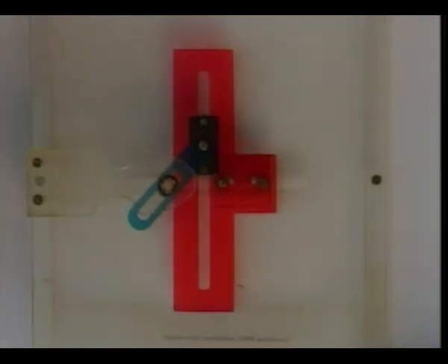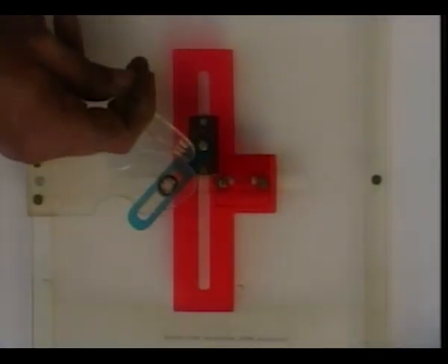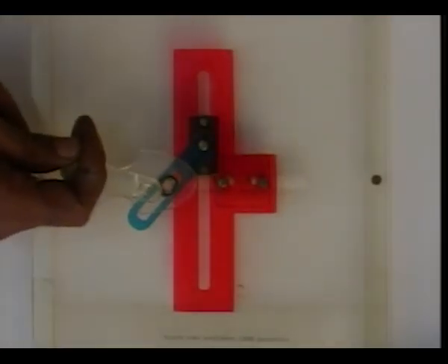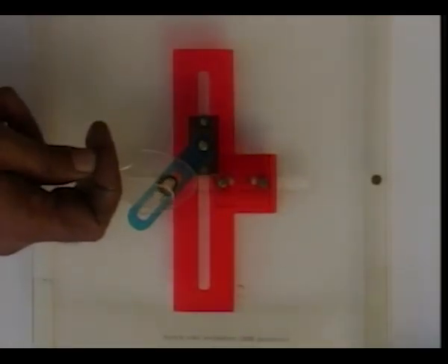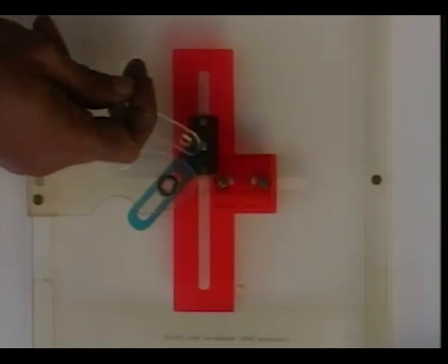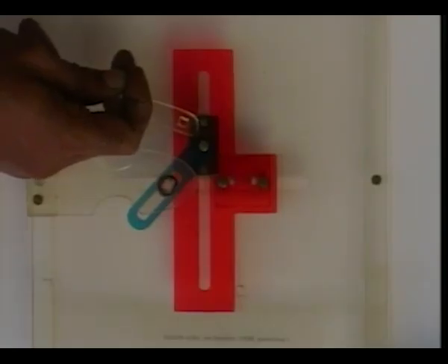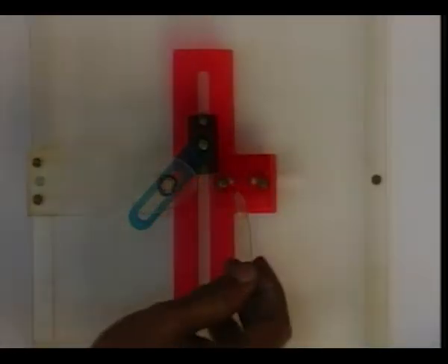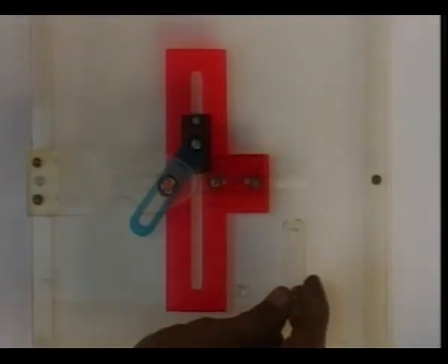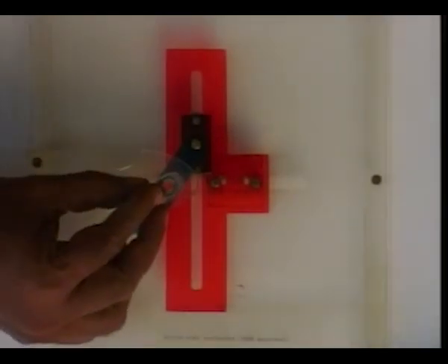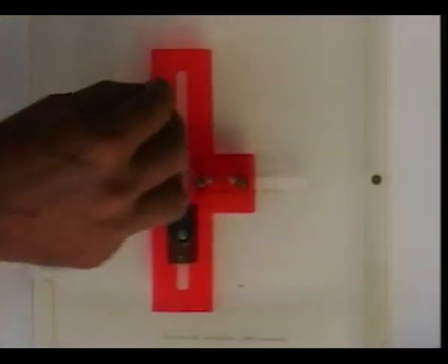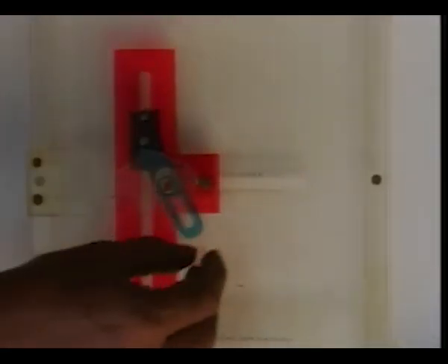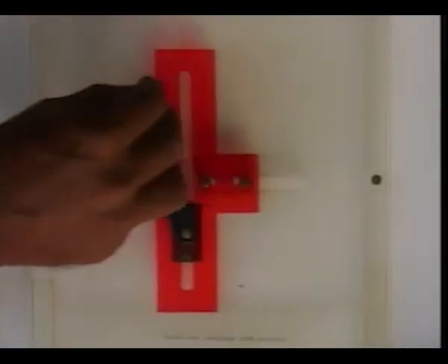This is the model of that Scotch-Yoke mechanism. This is link number 2, that is the crank, which has a revolute pair with the fixed link at this point. Another revolute pair between link 2, that is the crank, and this block is here. This block, link number 3, has a prismatic pair in the vertical direction with link number 4, and link number 4 has a horizontal prismatic pair with link number 1. Now if we rotate link number 2 at a constant angular speed, as we see, the red link, that is link number 4, is performing simple harmonic oscillation in the horizontal direction.